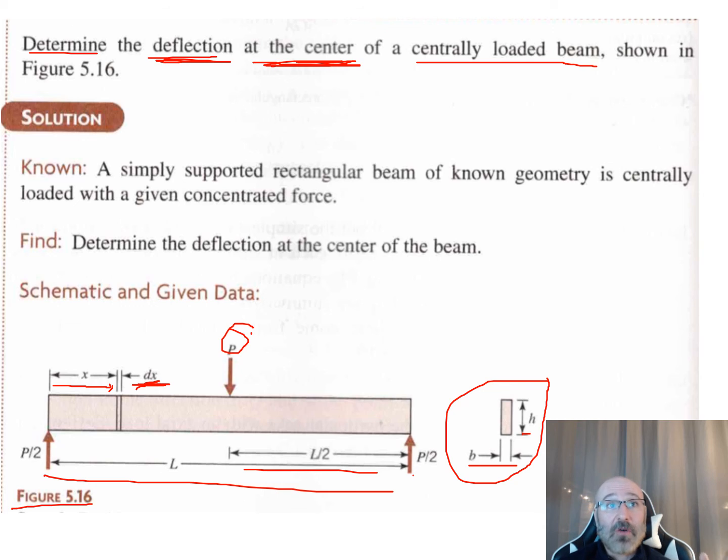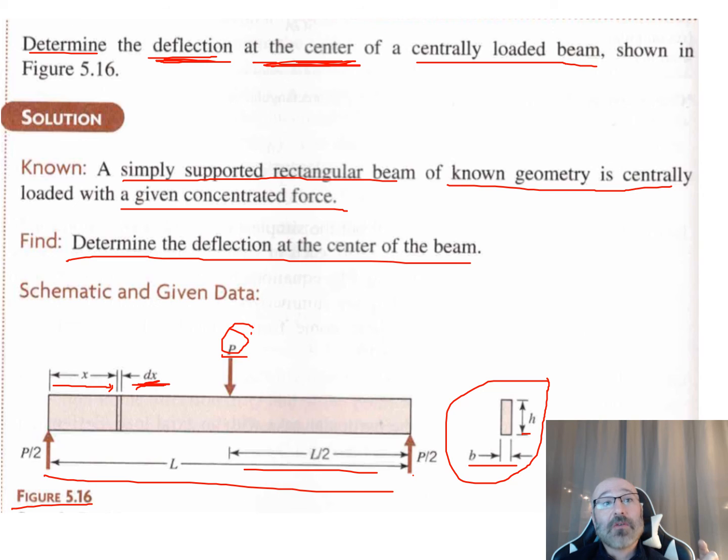So we say, well, what's known? It's a simply supported rectangular beam of known geometry. It is centrally loaded with the given concentrated force, and we want to find the deflection at the center of the beam. So let's create our setup page with that information.